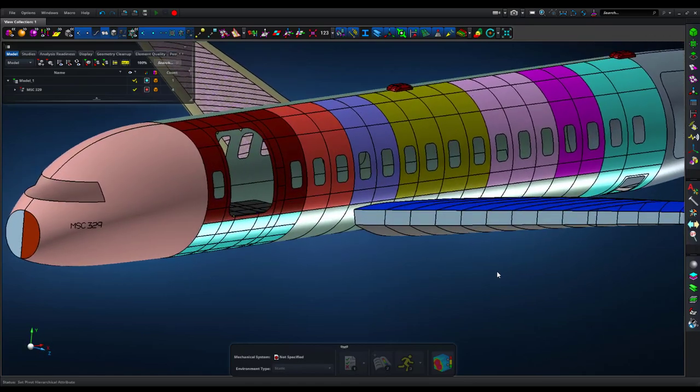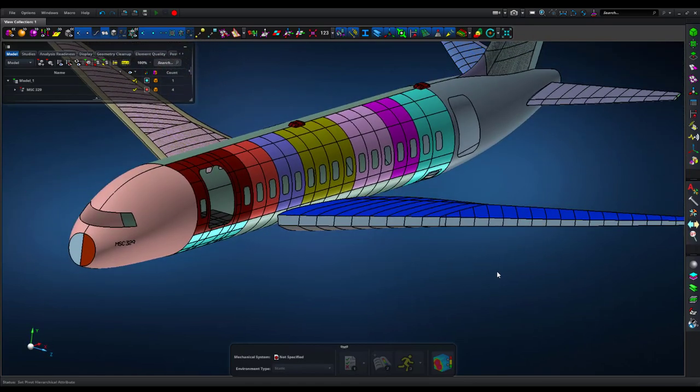In previous releases of Apex, users had to create composite layup combinations by hand each time, which took a substantial amount of unnecessary effort, especially on assemblies where you had to start over from scratch each time. Now, if you're using the same composite layup combination, you can create a composite ply pack, and Apex will remember this combination of composite plies, so that you can use them again on other parts of your model. Let's look at an example for the aerospace industry.